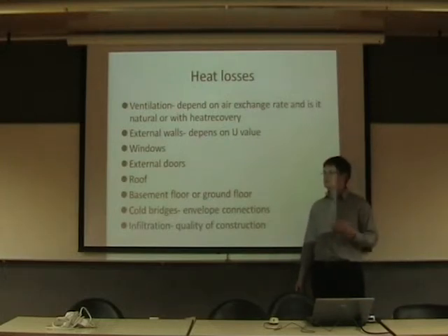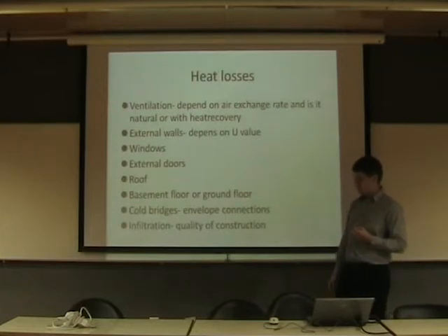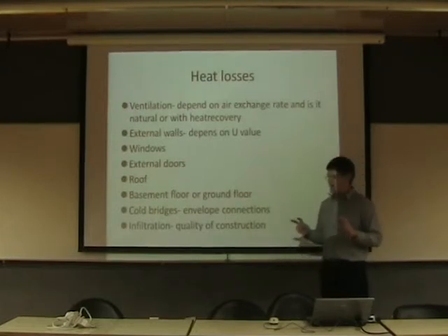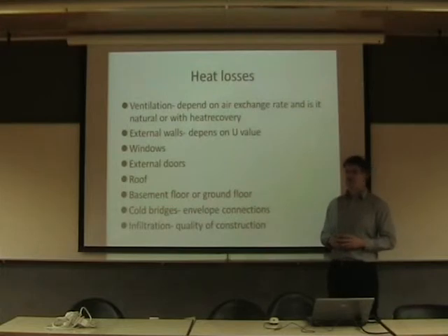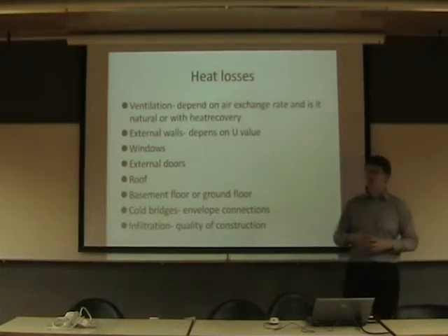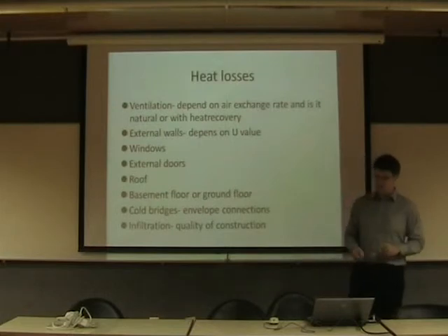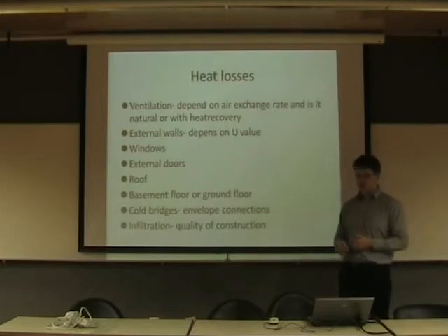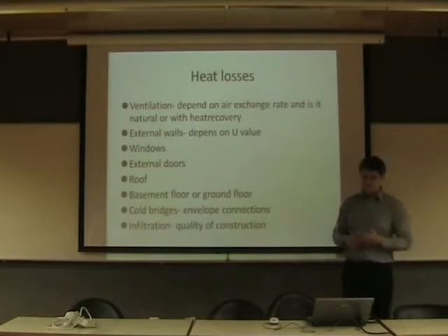With natural ventilation, the air change rate is about 0.5 times per hour. The whole volume goes out, and this volume of cold, fresh air comes in. Then we must heat it up, and it is a very big consumption of energy.